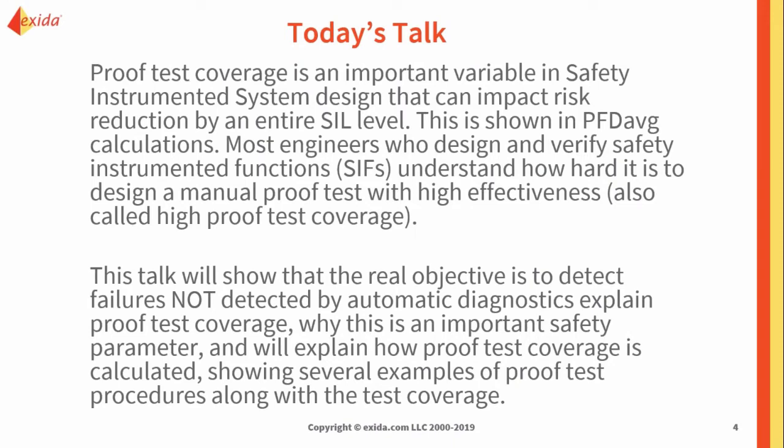But the reason you're here today, we're going to be talking about proof testing. Proof testing is a super important part of the management of your functional safety and how you manage your safety instrumented functions, or your SIFs. It's an activity that is required by the functional safety standards IEC 61511 and 508, and because of that, more and more end users are implementing proof tests.